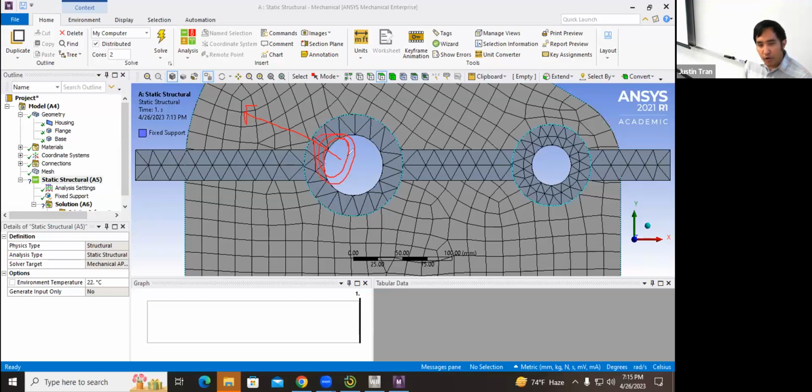Then what's going to happen is that you're going to have a higher concentration of force here, okay? On the part that's actually making contact with the rod as it's being pulled in that direction versus this side right here. Actually, this side experiences very little force because the rod is being pulled away from that surface. Okay, and so the idea with the bearing load is that we can apply the load on a circular surface like this, and most of the load, instead of being evenly distributed throughout the entire surface, is going to be concentrated on the part where a theoretical rod would be contacting that there. Okay, and so that's the load we're going to use in this case.